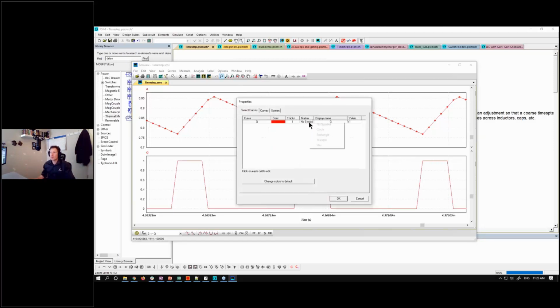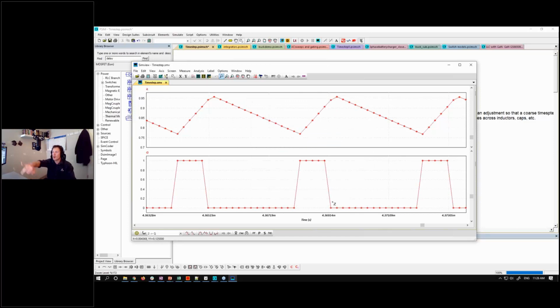So let's pull up a marker here. We've got this coarse resolution of the duty cycle, and this somewhat deformed current waveform, but the average value is right and everything is working and making sense. If we care about more resolution, beyond just whether this thing works, then we can start adding more time points, maybe 100 points per cycle or 200 points per cycle.